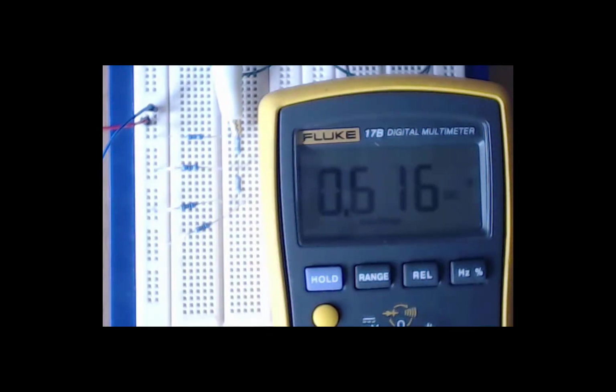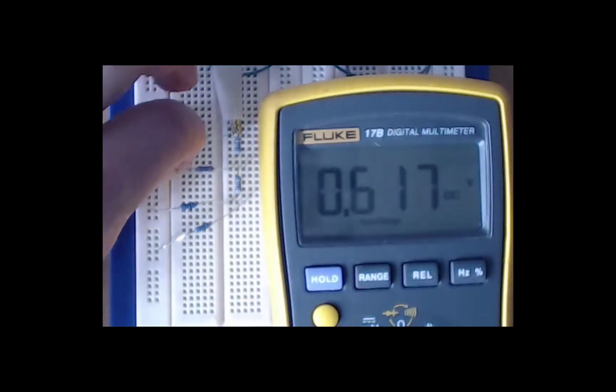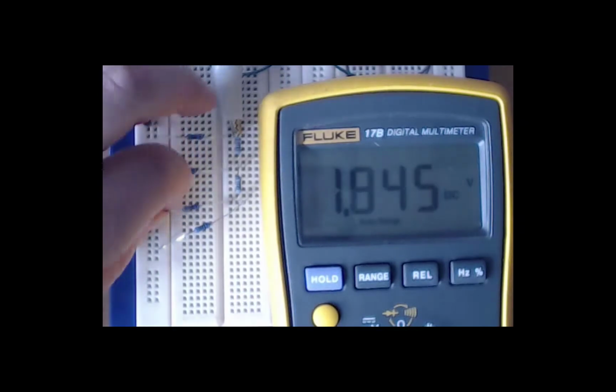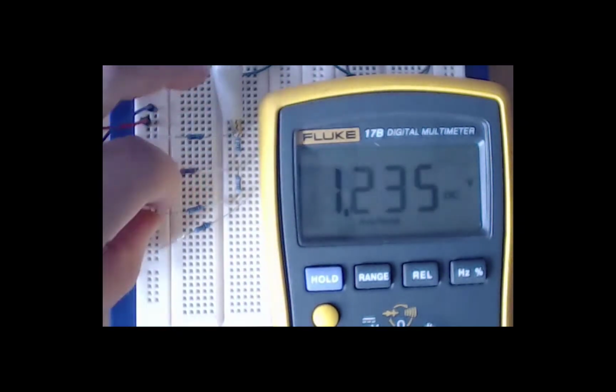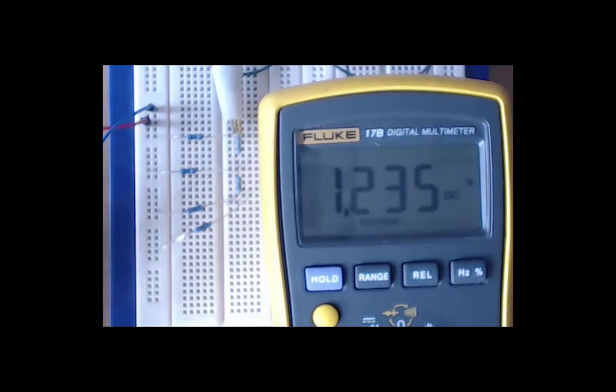If we do our calculation, we've got a 3-bit R2R DAC here, so n is 3, and 2 to the power 3 is 8. We see our binary value is 1. 1 divided by 8 times 5 volts gives us approximately 0.6 volts. So we're pretty close. If we increase our next one and step up by 1 and decrease this down by 1, it gives us about double what we had before.